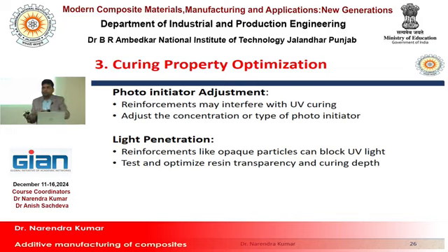Suppose before mixing the curing time was less, but after mixing the reinforcement in the resin, curing time may increase or decrease depending on the material that you mix in the resin. So you need to adjust this value. You can add photoinitiator to ensure proper solidification.